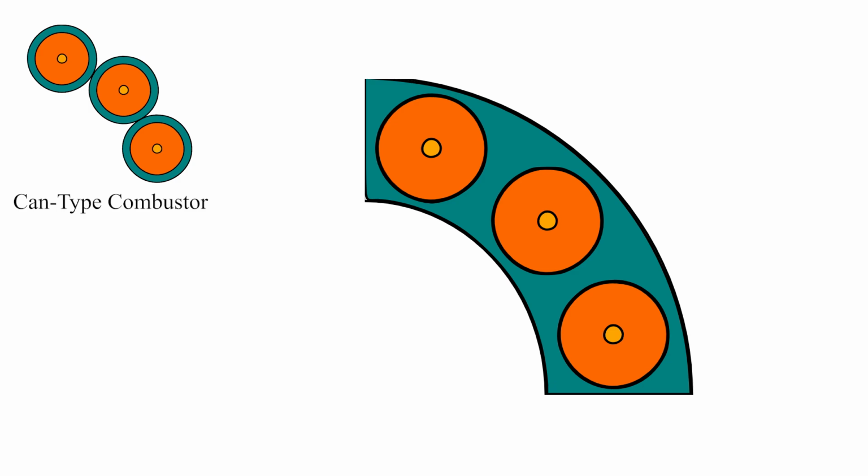flow circumferentially. The exit flow from the canannular combustor generally has a more uniform temperature profile, which is better for the turbine section. It also eliminates the need for each chamber to have its own igniter. Once the fire is lit in one or two cans, it can easily spread to and ignite the others. This type of combustor is also lighter than the can type, and has a lower pressure drop, on the order of 6%. However, a canannular combustor can be more difficult to maintain than a can combustor.